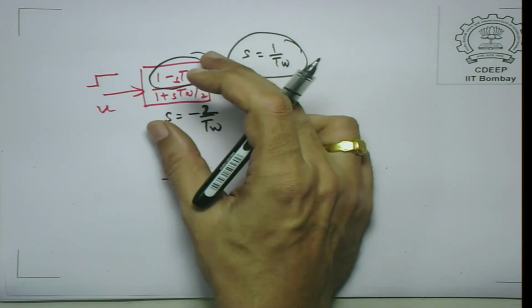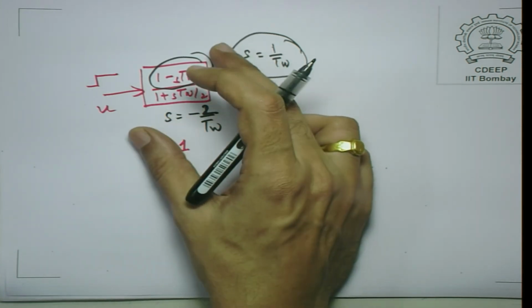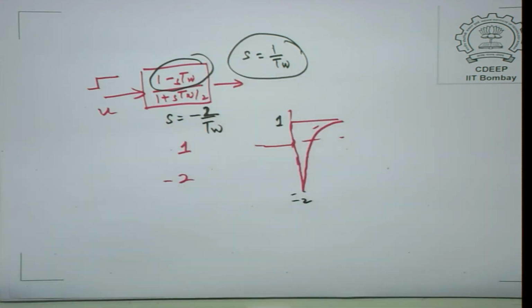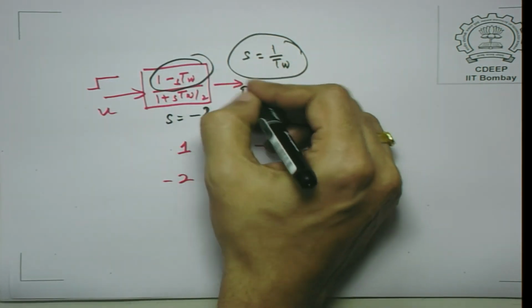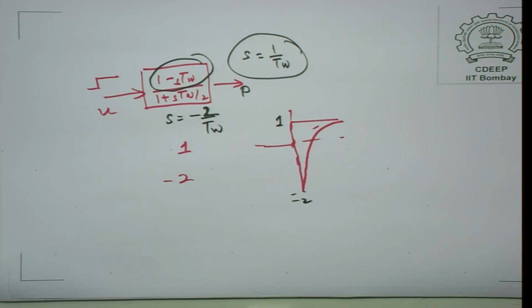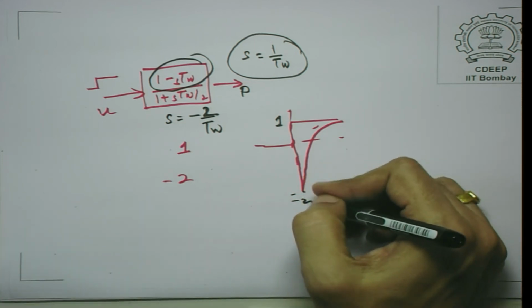This model which we have got of the hydro turbine is highly simplified. Okay. The model of the behavior of the power as you open the gate is highly simplified in this transfer function, but even with this, for argument's sake, if we take the simplified transfer function, it has got quite a peculiar behavior. The power in fact may drop.